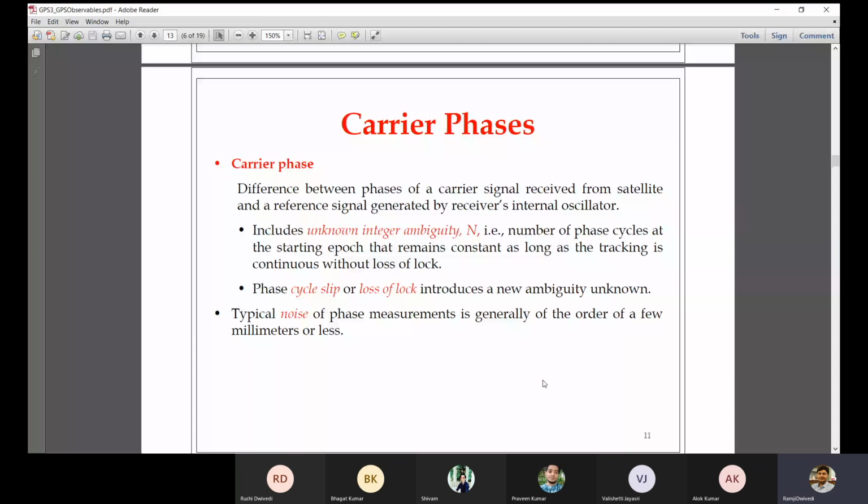Okay, at the same time the receiver also opens up the navigation file, just like a small pocket book. It opens up the various pages and tries to get the exact information for calculating the satellite coordinates at the time, or at t is equal to t, where it wants the receiver position.